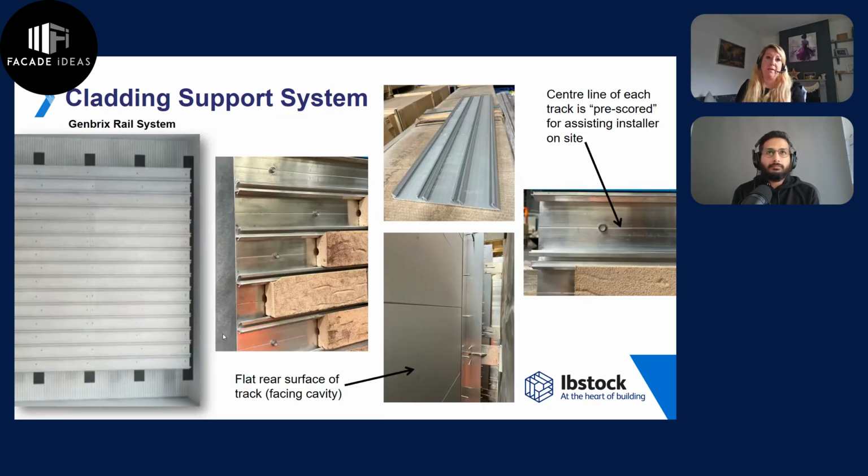And the reason for that is because it uses a flat-backed 3-course tray to accept the brick slips. So you can see there it's not the same as the Mech-Slip, but we use it as a 3-course. But you don't have to build your buildings in multiples of 3. We do offer a single track course as well to accept the slips, so we can obviously have different dimensions.